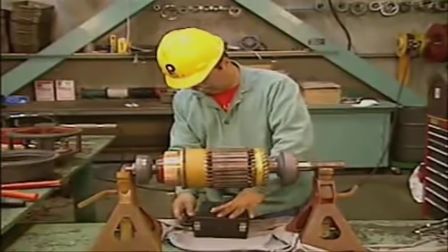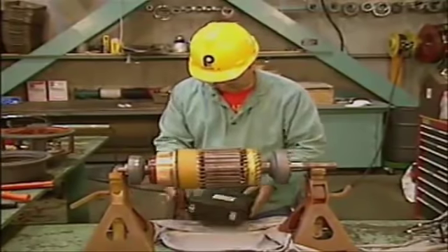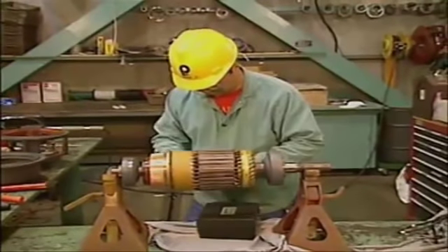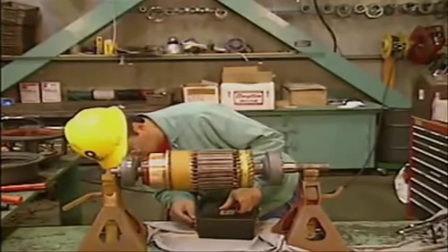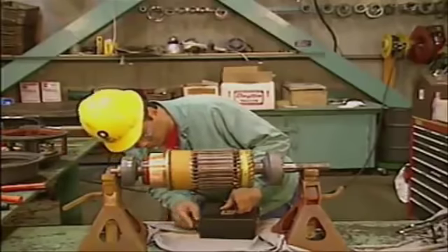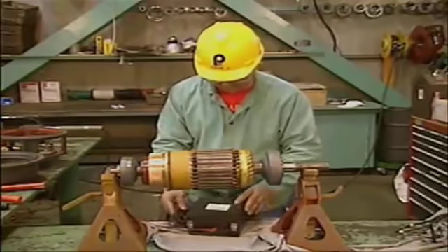After the armature has been checked for shorts, a meg-ohm meter can be used to test it for grounds. The procedure for this is covered in this unit in the troubleshooting part of the motor maintenance topic. To see a brief description of how this test can be made, select Test. When you're ready to continue the lesson, select Go.